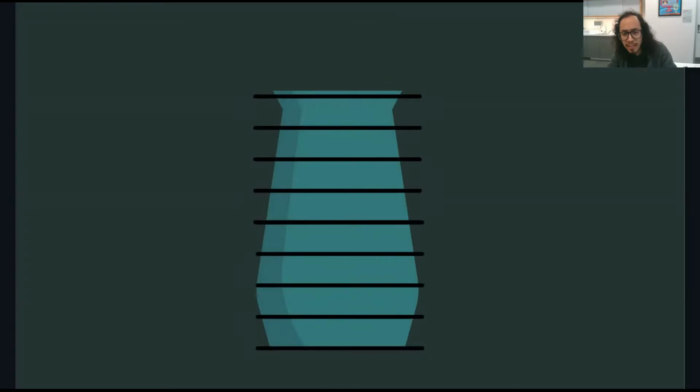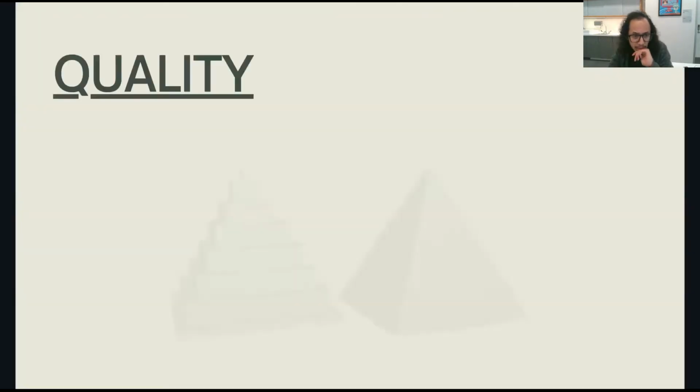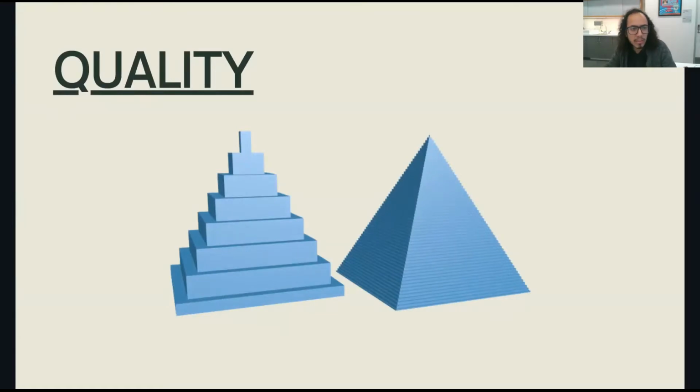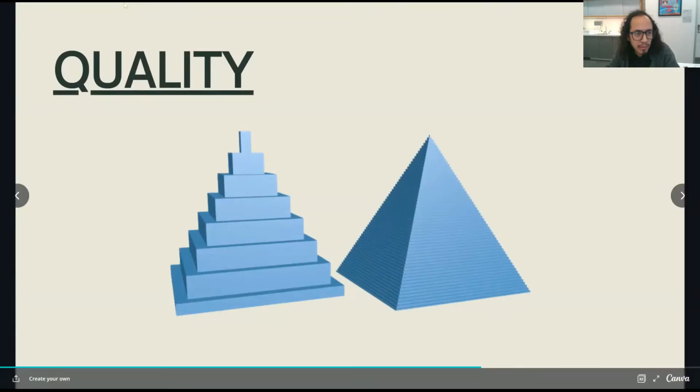Here's an example of how it slices it. It does very fine layers. They're not going to be this wide, but it splits your object into horizontal layers. So let's switch over to Thingiverse real quick, so you guys can see where we can download the files. We'll import them into Cura, and then we'll talk about the settings in Cura.